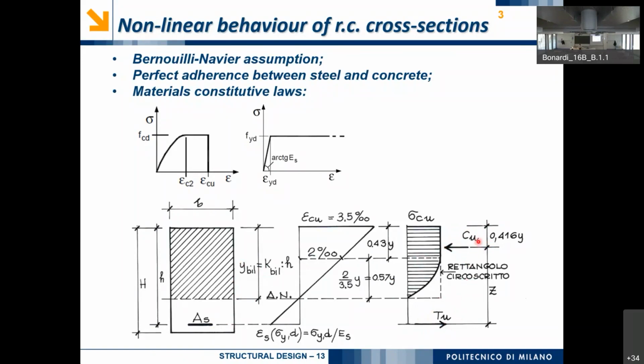According to this couple of forces, we have the possibility to balance different levels of compression forces acting on the structure at each cross section, and of the bending moment. The bending moment will be simply the product of each of these forces, if they are equal, times the effective length. Otherwise, if they are not equal, there will be some resultant force.